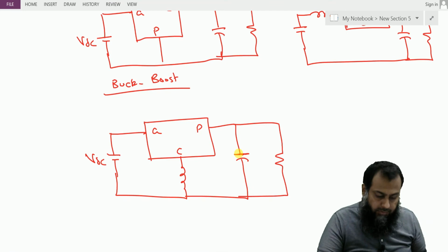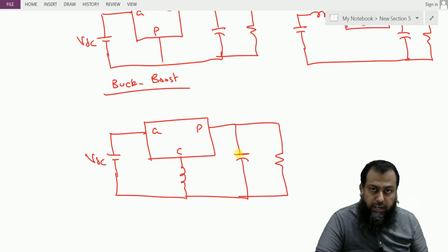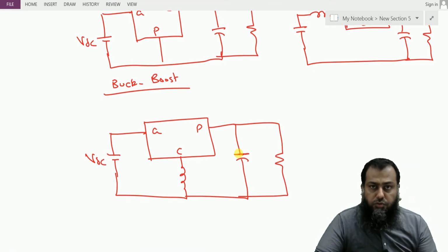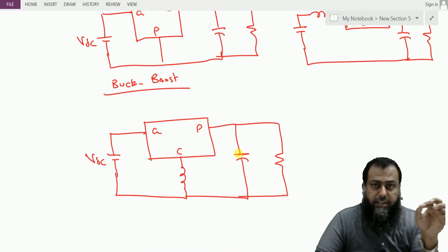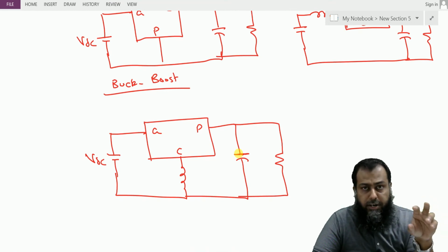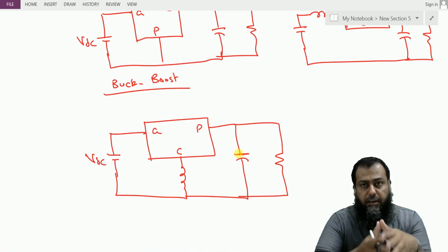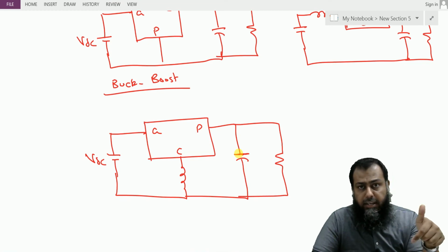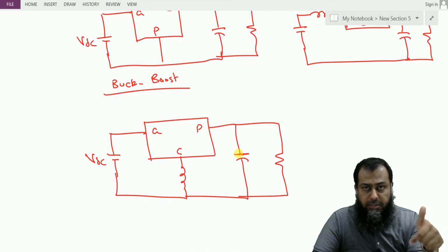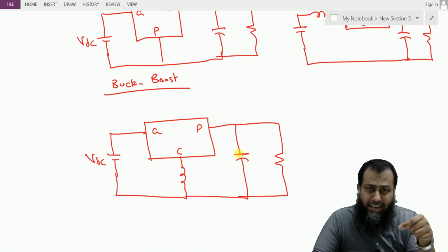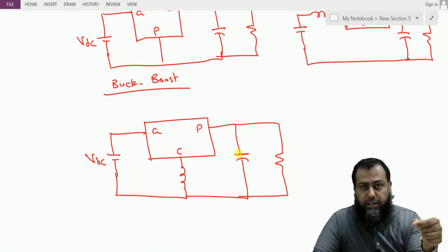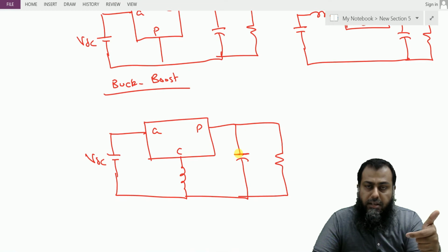So now we have discussed these two scenarios. Let me summarize these two simulation strategies. Power electronic circuits can be simulated by using switches that consist of diodes and MOSFETs or some other related switch. That cycle to cycle conversion gives us very detailed information about the circuit transients and the steady state information. But most of the time it is not much required, because cycle to cycle measurements at a steady state value give us no new information.